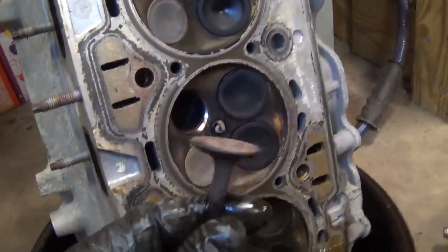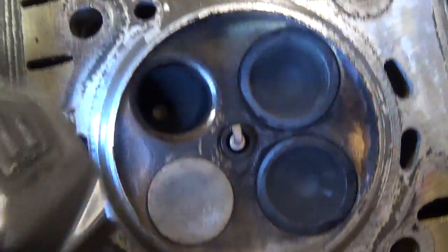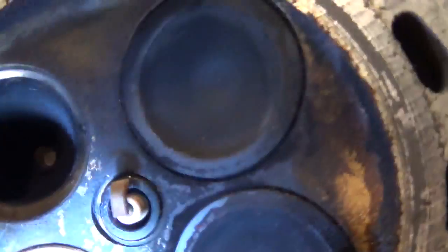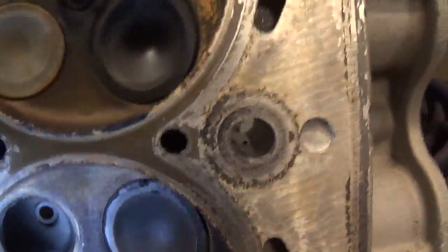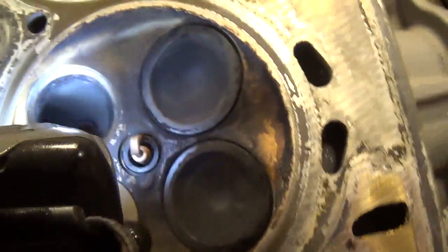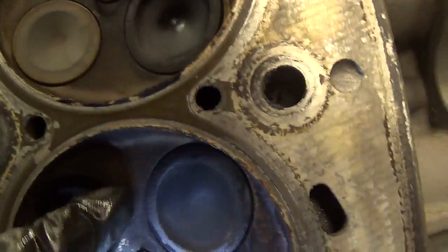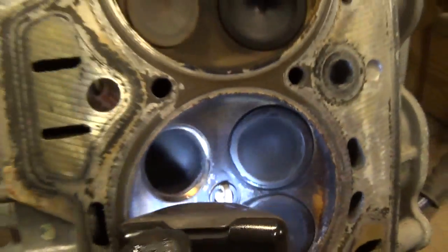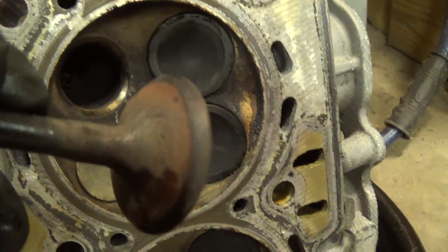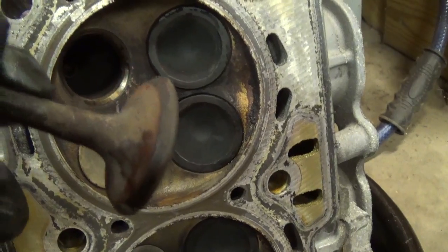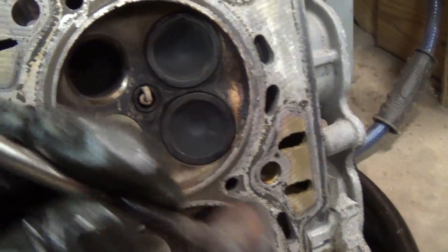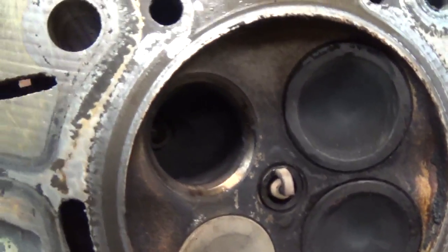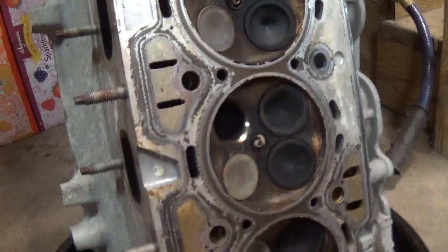Alright, so I got the top exhaust valve out, the real bad one. To the untrained eye, it might not seem like anything's wrong. If you put a little light on here, the problem is the valve seat. There's supposed to be a nice sealing surface all the way around, and we can see that sealing surface has almost disappeared right there. It's a hard shot, and you can see on the valve right there it's not sealing, it's not shiny anymore. So that's our issue. I don't know what the machine shop is going to do. These seats are replaceable, I think. You can buy them at least. So we'll go from there, but that's our issue.